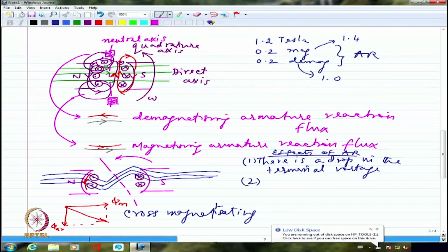The sparking occurs to some extent because of this, and to some extent because the machine conductors have inherent inductance. The inductance will not have any effect if it is carrying a steady current. But I am looking at the current transfer from plus I to minus I when the conductors are shifting from the south pole side to the north pole side.